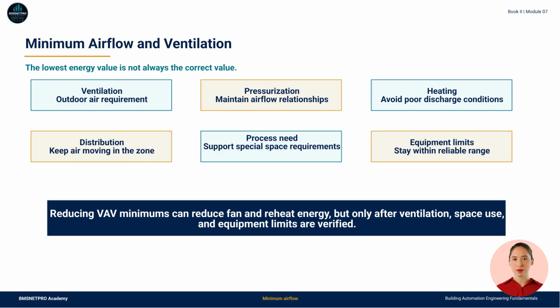Before changing minimum airflow, verify space use, occupancy assumptions, ventilation requirements, terminal capability, reheat strategy, and any special pressure or process need. The lowest airflow value is not automatically the correct value.